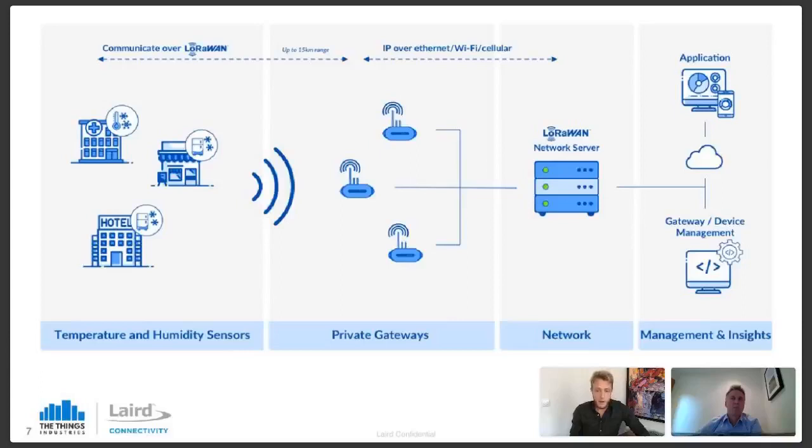The network server implements the server side of the LoRaWAN specification. And what's good to mention here is that LoRaWAN devices don't have an internet connection. So it's not that there's any internet protocol in there. So all the things that you get for free in internet, such as IP addresses, transport control mechanisms like counting frames, recovering from frames, and routing of packets, that is all part of the LoRaWAN specification, and so you need a network server to implement the server part of that.